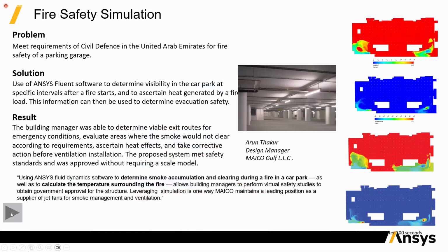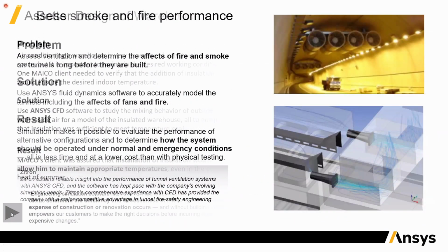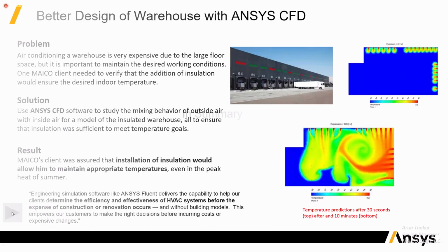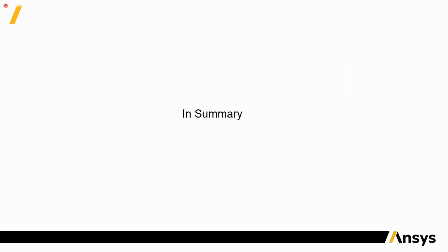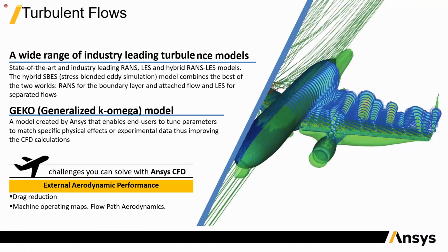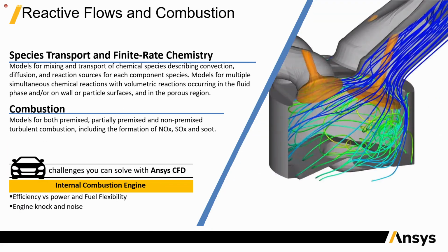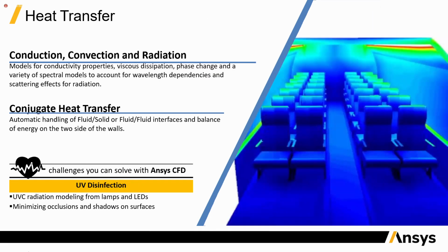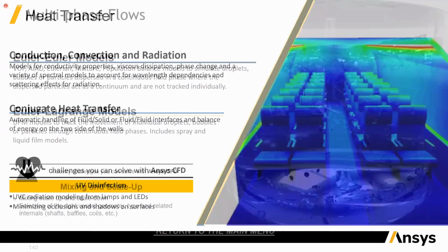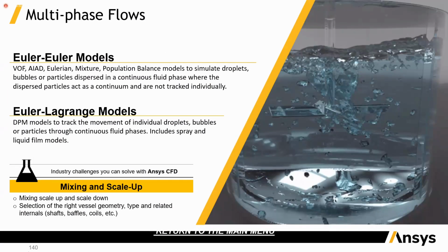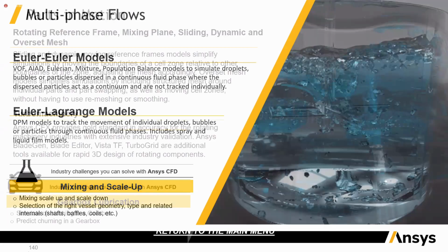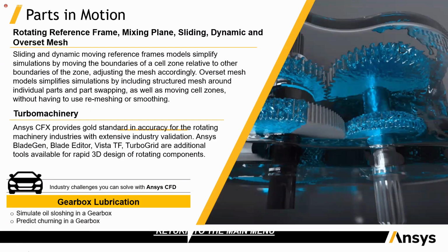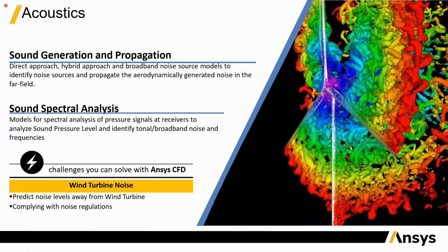Fire safety simulation, smoke simulation, warehouse analysis. My time is almost up. So in summary, using CFD analysis, you can analyze turbulence flows. You can analyze reactive and combustion flows. You can understand heat transfer, whether it be conduction, convection, or radiation. You can do multi-phase analysis, solid to liquid, liquid to gas, gas to solid. Moving parts, rotating equipment, turbo machineries, acoustic, aeroacoustic analysis using ANSYS.